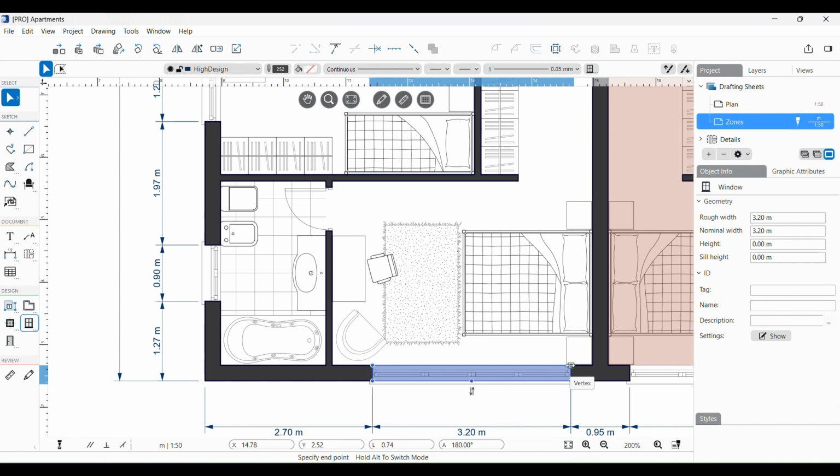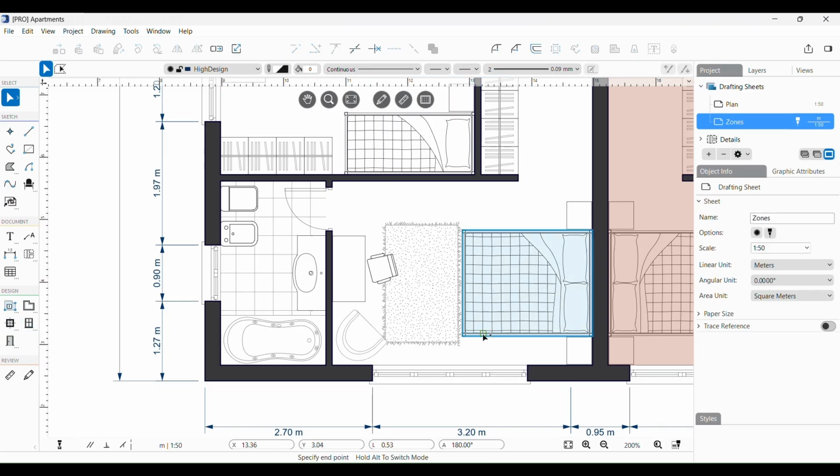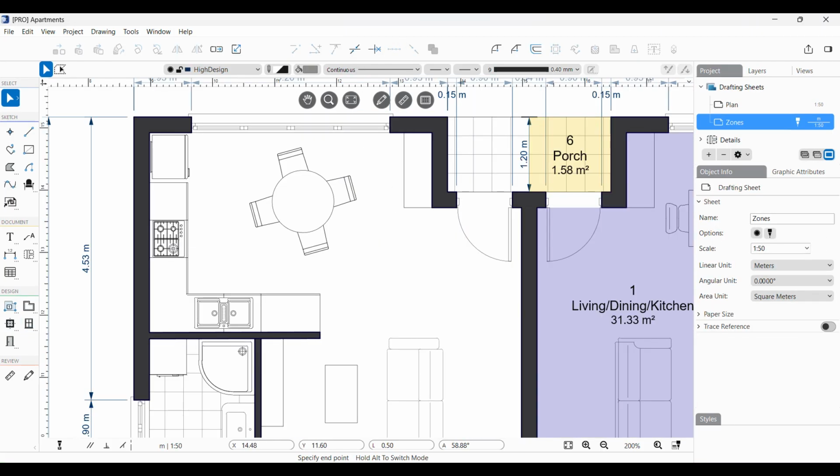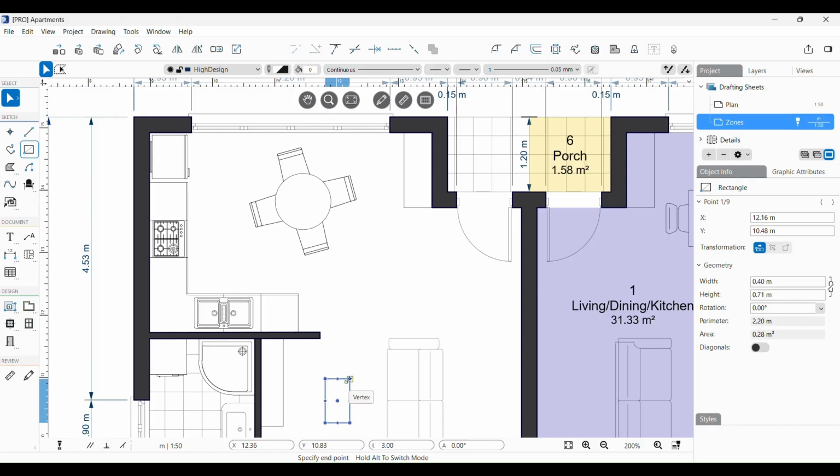You can perform this action graphically by clicking on the new desired location of the endpoint, or numerically by entering the new length and angle values of the selection in the L and F fields of the input bar while moving the endpoint. Objects that have a center: rectangles and polygons, arcs, circles, ovals, symbols, images, text notes, tables, viewports, and title blocks, groups. These objects can be resized by graphically changing their geometry.